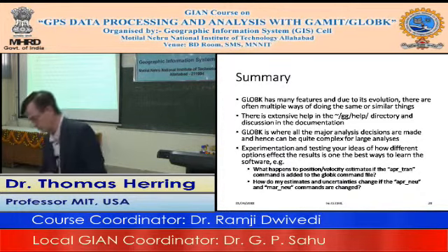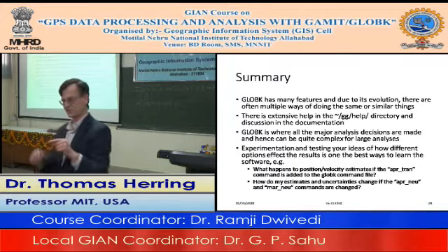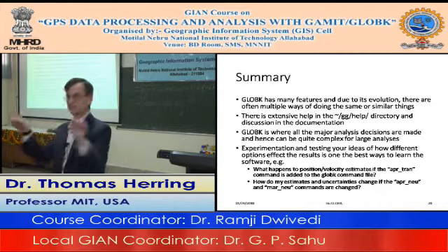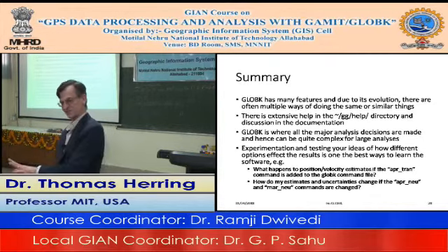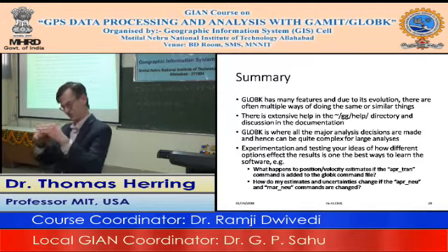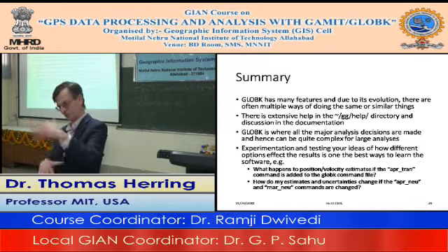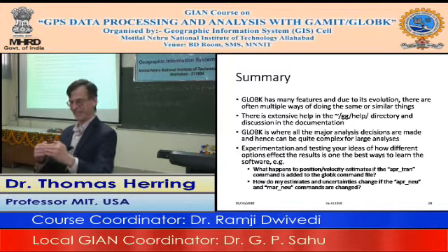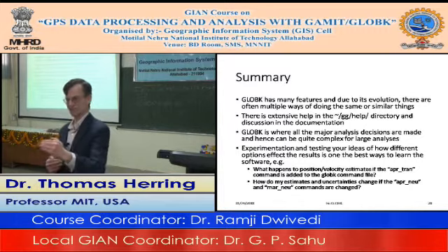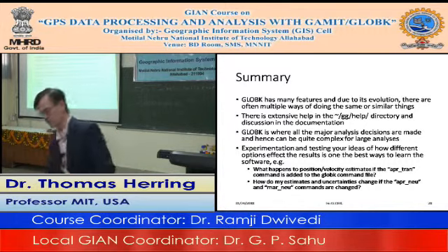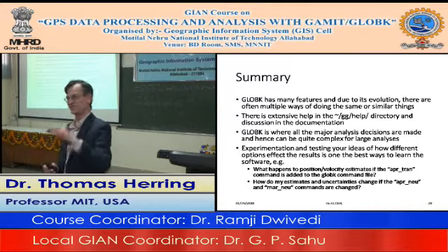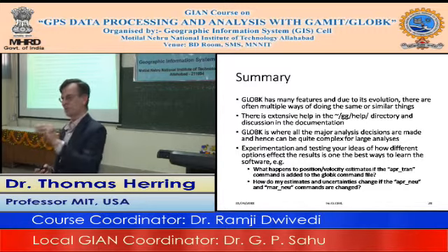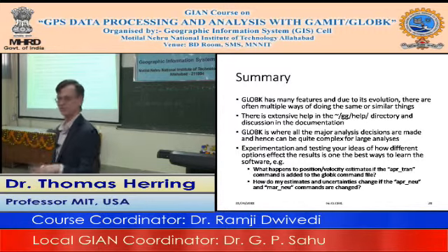Yeah, so if you want to do time series, you can set up 30 individual GLOBK runs, one for each day, and generate the time series. Or, if you want to do the velocity solution, you would have just the one GLOBK run with it all done. Or you can have just one GLRED run that will generate the 30 commands to run GLOBK. So that's all GLRED is doing: it's just an interface that sequentially runs GLOBK on multiple things. But you can do it by hand if you wish to. You don't have to use GLRED.